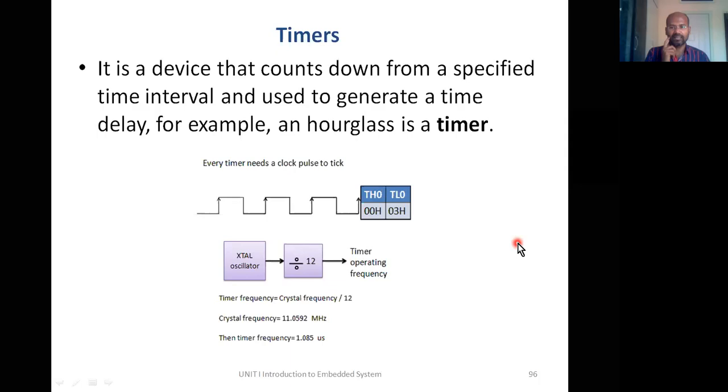That is possible with hardware called a timer. A timer is hardware which is present in the microcontroller, in the same IC. It is basically a counter. It takes the clock pulses which are coming from the clock generation unit, and it starts counting those clock pulses. If your clock is a 1 megahertz clock, then each clock pulse has how much duration? 1 microsecond. So this counter circuit is called a timer.